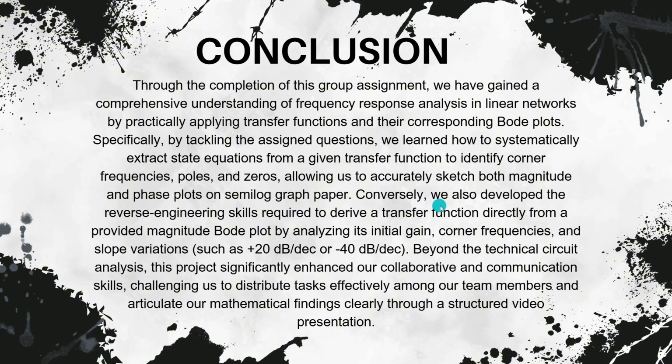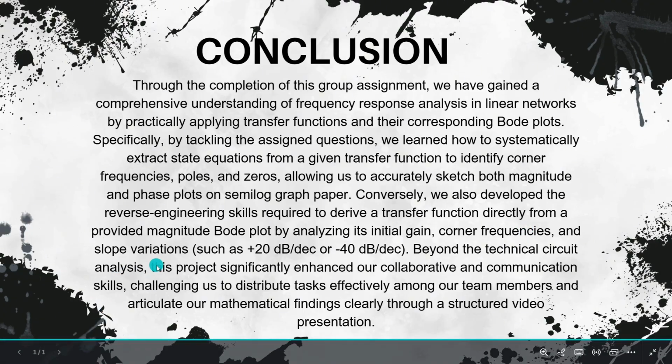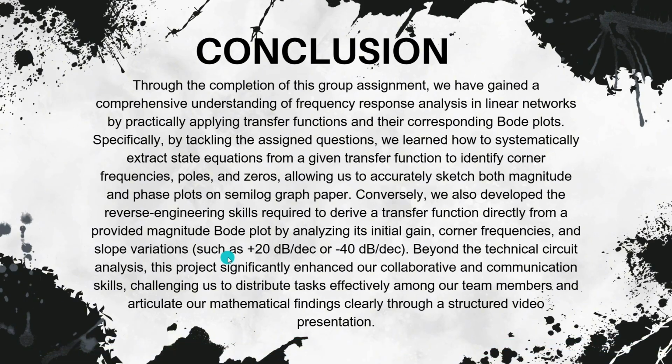Conversely, we also developed the reverse engineering skill required to derive a transfer function directly from a provided magnitude Bode plot by analyzing its initial gain, corner frequency, and slope variation, such as positive 20 decibel per decade or negative 40 decibel per decade.